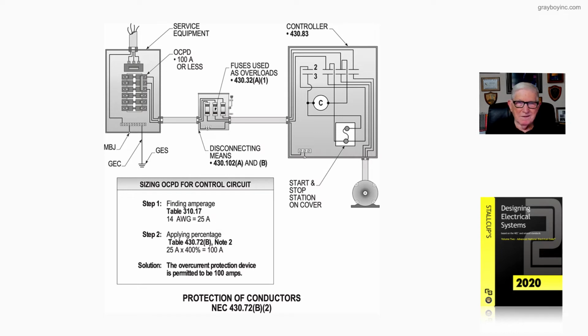And notice at the left of the table, the first column is your control circuit conductor sizes. And then, of course, if we're using copper, number 18 would be 7, number 16 would be 10. And that'd be the maximum protective device. Number 14, though, notice on a 100 amp device, we would go to the note 2, really, and we would get free air in Table 310.17. That's in the 2020 edition. In the 2017 edition of the NEC, we would look at Table 310.15B as in boy, 17.